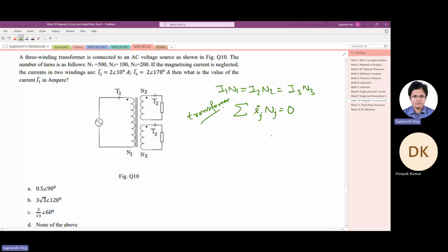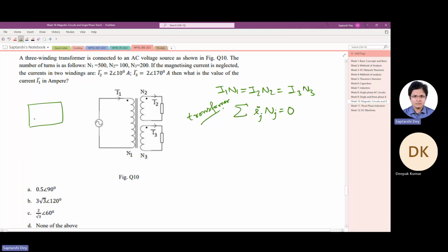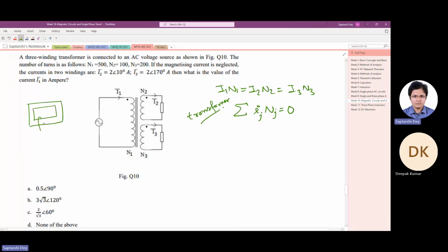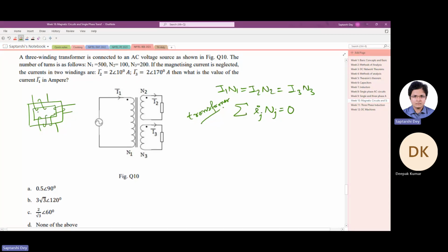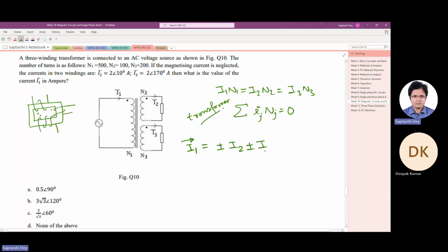Okay. So the best way of solving this kind of circuit is to draw a transformer by yourself, then look at the dots that have been given in the question and draw the windings in that fashion. Obviously not during the exam, but for your understanding, the way the dots are given, you draw the circuit in that fashion, put the dots, and then find out in what direction. So this question actually not only asks you about the current transformation, it also asks, see, they're vectors, right? So the direction matters. Basically, find out the plus and minus.